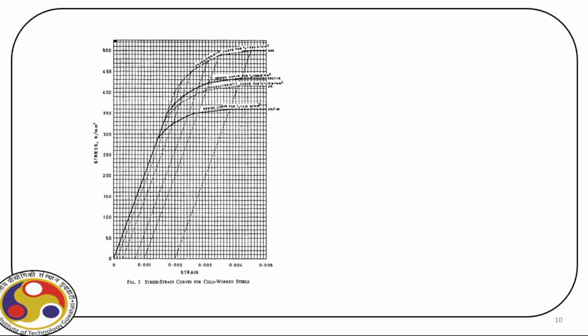Now, again I go back to this stress strain curve. These are available in SP16. Recall we discussed this earlier. This is a design aid to IS 456, and there are different design charts and tables provided in this codal provision, and then actually we can use this to find out the stress corresponding to different values of strain, right?